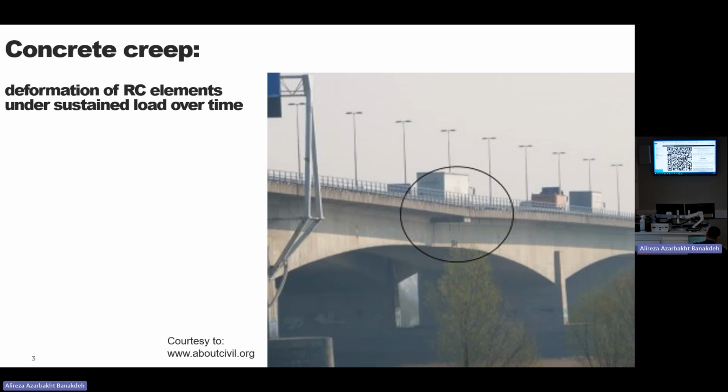Who knows what's shrinkage? Get smaller. Yeah. When you mix concrete, you have aggregate, water, and cement, right? And sometimes some additives. Anyway, when you pour the concrete, it will get dry. Okay, you need to cure it, you need to moisturize it, but anyway, the inherent water will be vaporized. And because of the loss of water, the volume will be smaller. So this means shrinkage.